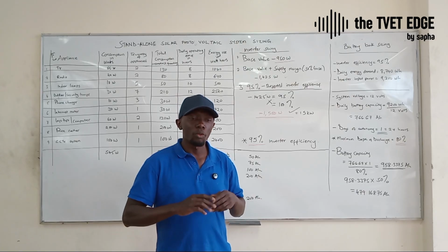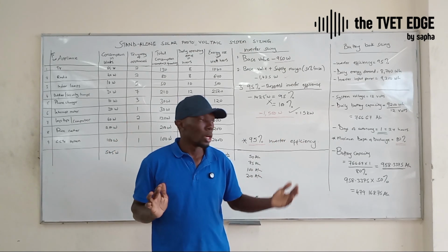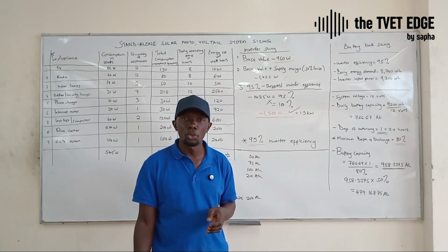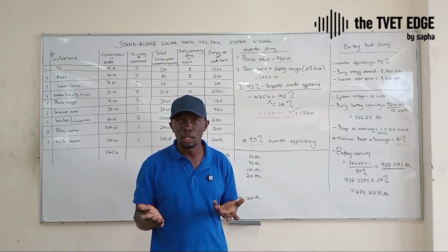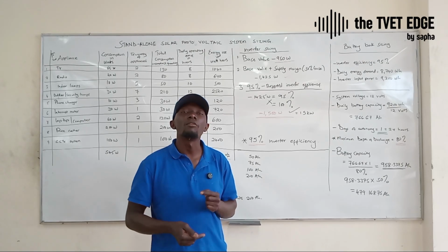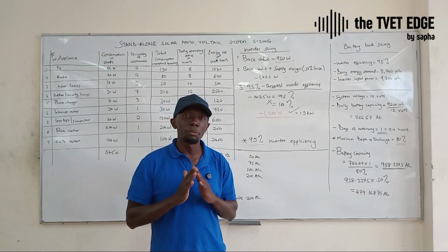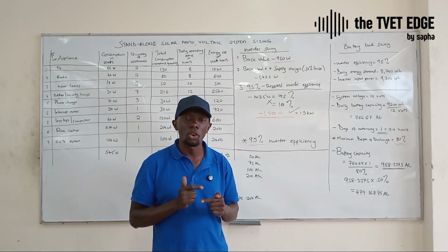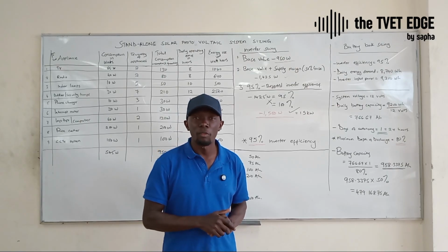The first way of solving that issue is ensuring you have a bigger bank. A bigger bank means, if, for example, in the evening you are at 100%, in the morning you will not have drained all the way to 20%. You'll be having enough, let's say 40% or even 45%, not draining your system all the way to the bottom mark. That means you'll have fewer charge cycles, and fewer charge cycles means your battery will last longer. If your batteries are put on an extreme, continuous charging and discharging cycle, first, they degrade faster. I hope I've explained myself well.